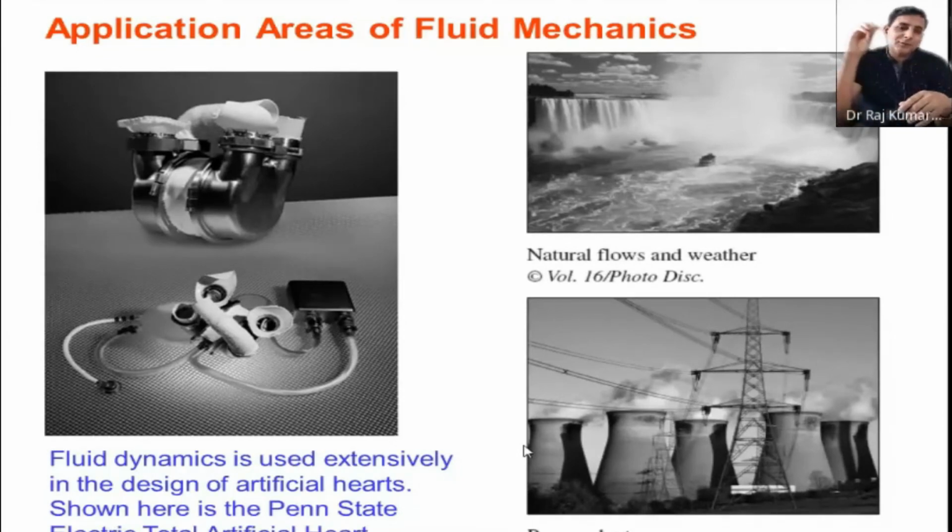So there you need a statistical approach in all these pollution control ways. Fluid mechanics helps in designing your tower shape, that is, how you give the natural draft so that at the bottom you just give a small blower and your gases can go up with a very high velocity. You see this tower has a very huge area at the bottom, and on top you have the narrow one. This is called natural draft.